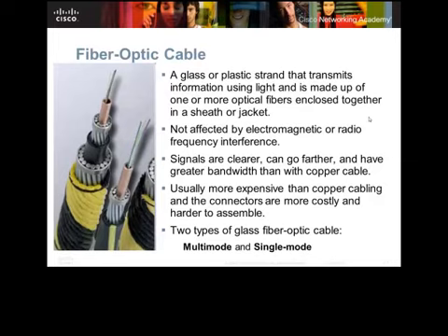There are basically two types of fiber optic cable that you should know about: multi-mode and single mode. Multi-mode has a bigger core. Because it has a bigger core, we are going to have more dispersion of our light. This helps for going around bends and twists, but we do not get the distances or the speeds. Single mode fiber has a smaller core. We must keep the cable relatively straight, but because of the smaller core, we can have longer distances and we can have greater speeds with the single mode. Single mode is going to be a little more expensive than the multi-mode fiber as well.